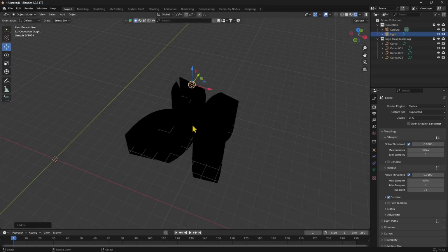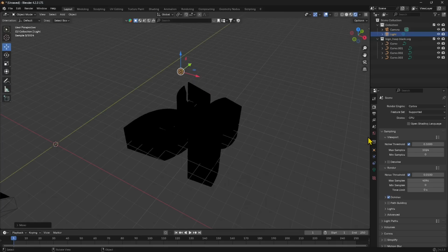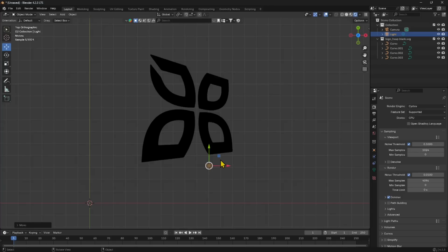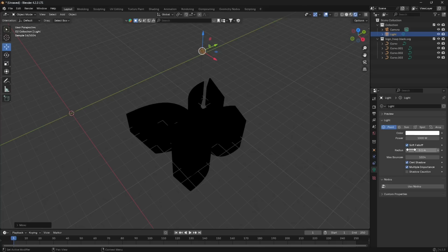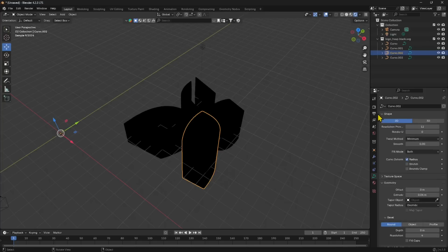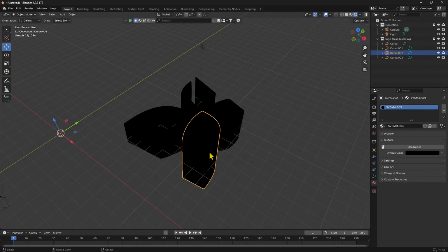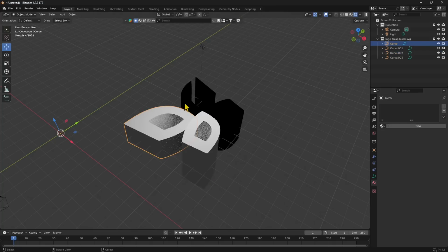All these topics are covered in the Blender video course. I'm going pretty quick here just to show you a little bit of how everything is working. And let me increase the intensity, the power of the light. Nothing happens, so I guess it's the material. So I'm gonna go in the material. You can see it's pretty black, so I'm gonna change it into something a little bit brighter, and I will start to see something. Again, these are just some examples.